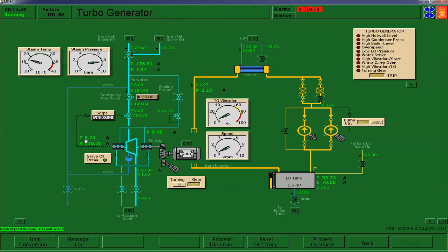And what I am watching is the RPM. I'm watching the governor, which is 100% open right now. And we're emitting steam. I also need to kind of keep an eye on my lube oil tank temperature, which comes up quite high on this. When everything's normalized, it's around 60 C, so we're still fairly cool.